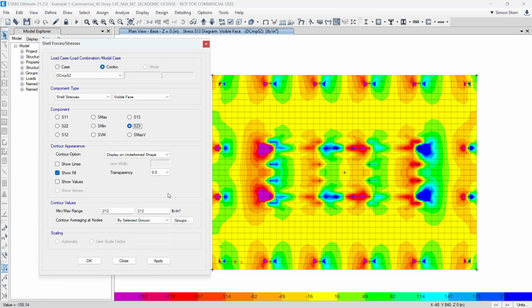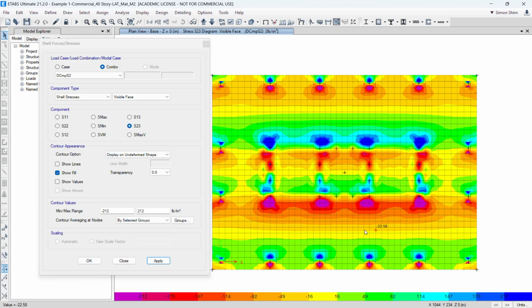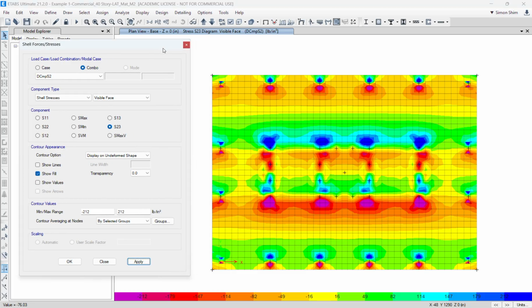This is the shear stress direction, right? All right, so for now, this is just the checking procedure. We might need to increase the mat thickness a little bit at the bottom under the wall, or, assuming this much shear stress exceedance, we may consider shear reinforcement. We'll talk about it in more detail later if we have a chance.